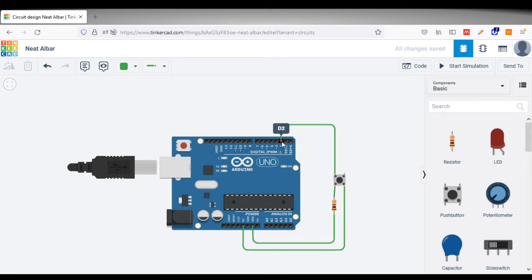So if I am reading from pin number 2, you will get it as 1 or digital 1. And when you are releasing the switch, the same pin number 2 will be connected through this resistance to ground. So when I am releasing the switch and I am reading the data from pin number 2, I will get the data as digital 0. So that is how we have implemented the same circuit I have shown in the previous PPT using this TinkerCad. So the circuit diagram is implemented.